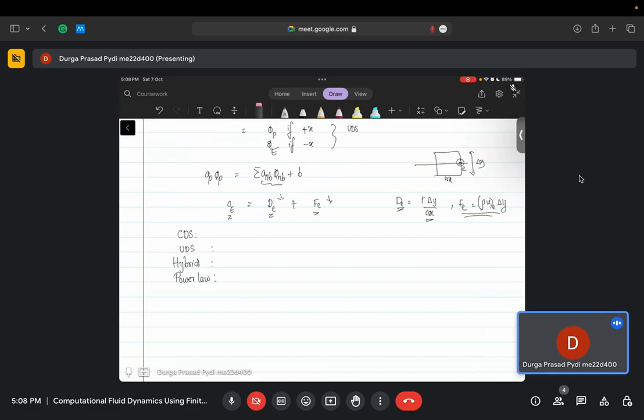Say we have dE times some function plus the standard form, which is 0 comma minus Fe. So this essentially takes care of your upwind scheme. When you have a pure upwind scheme, you just don't need any of that information, and you capture it in this function A, where A is a function of P. P essentially is your Peclet number.